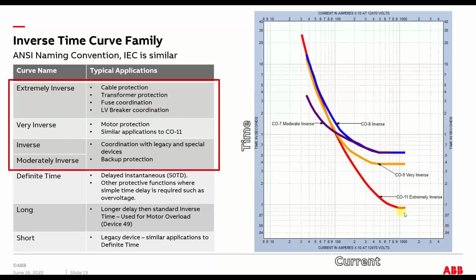That's a very good curve to use if you have to coordinate with a fuse, or a low voltage circuit breaker, transformers to some extent. So it's a pretty often used, this extremely inverse curve. So that might be a good one to start with in a lot of applications.